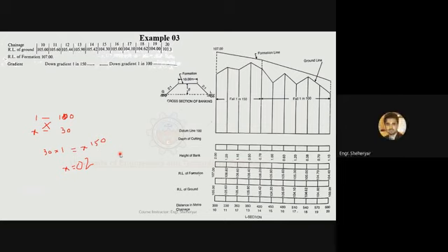0.3 सर। 0.3। सो अब इसके ऑनवर्ड्स आप देखेंगे कि 0.3 का डिफरेंस आ रहा है। 106.2 minus 0.3 you will get 105.9, 105.9 minus 0.3 105.6, 105.6 minus 0.3 105.3 and so on। ठीक है आखिर तक। अभी आपके पास आ गई रिड्यूस लेवल ऑफ द फॉर्मेशन। अब इससे आप हाइट ऑफ बैंक और डेप्थ ऑफ कटिंग कैलकुलेट कर सकते हैं।